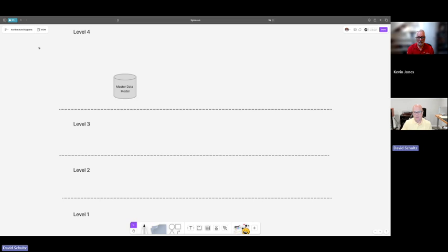Now, it doesn't have to apply to a formal standard, but what I'm getting at is that regardless of what the equipment is and how it's going to be exchanged or what it's doing, try to come up with, sometimes it's known as the data dictionary, but everything is going to be utilizing the same type of common data structure. Are you referring to or thinking about the semantic hierarchy that we typically use from ISA 95 Part 1?